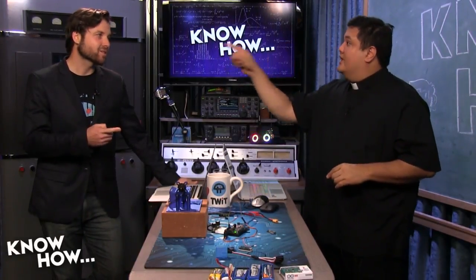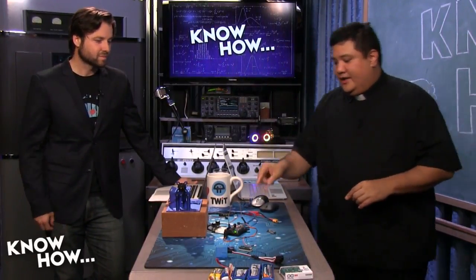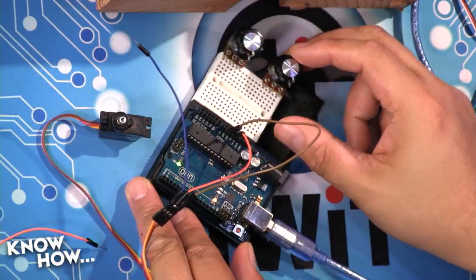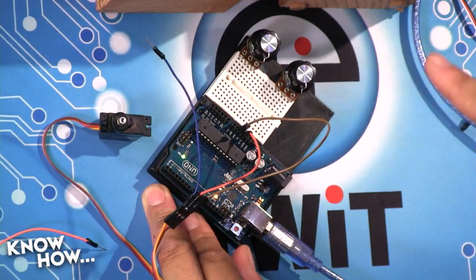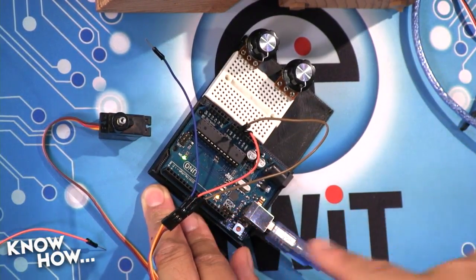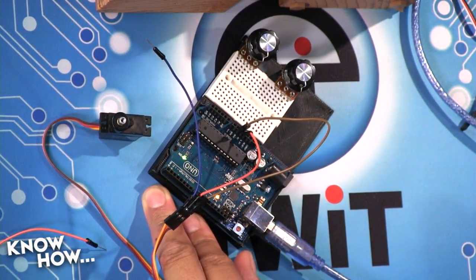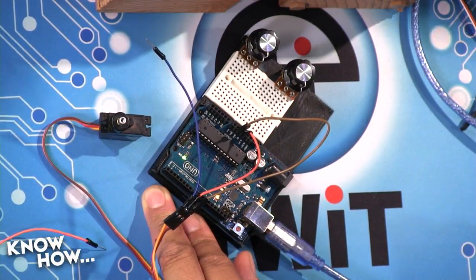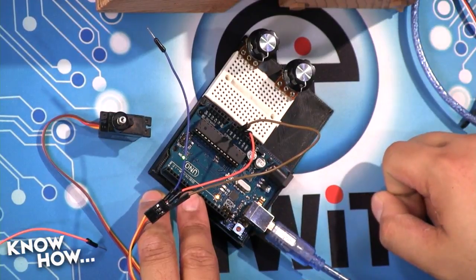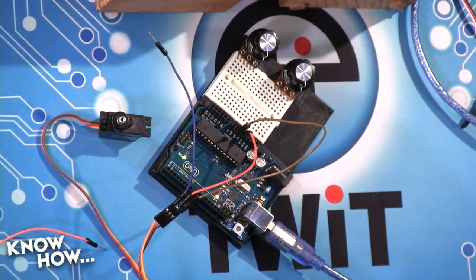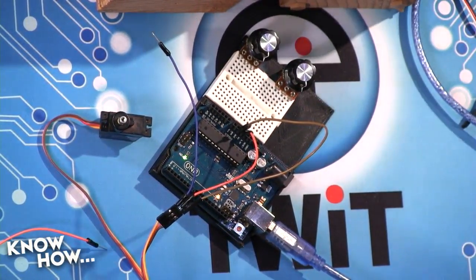Now I could change that. Exactly. I could change it, but I don't think you can get a shot of this, Alex, but if you go to the overhead, some of these pins have a little tilde next to them. What does that mean? That means that those outputs can do PWM. Oh, okay. So you see 9, 10, 11 do, and I could use 3, 5, and 6, but not use 7 or 8. You could technically do PWM with the others, but yeah, use one of the PWM pins.